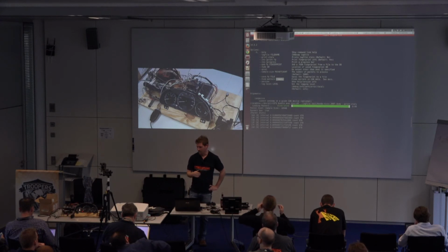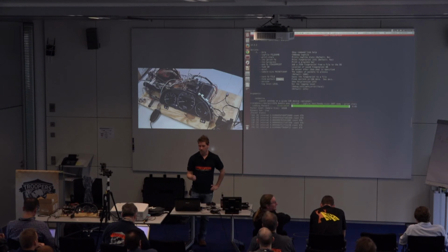And then have it listen to a live bus. Say you're trying to reverse engineer door unlocks, you would just follow that pattern. Lock, unlock, lock, unlock, lock, lock, lock, unlock. Quit it and it'll go, oh, here's your code, and here's the byte offset. It finds it for you.